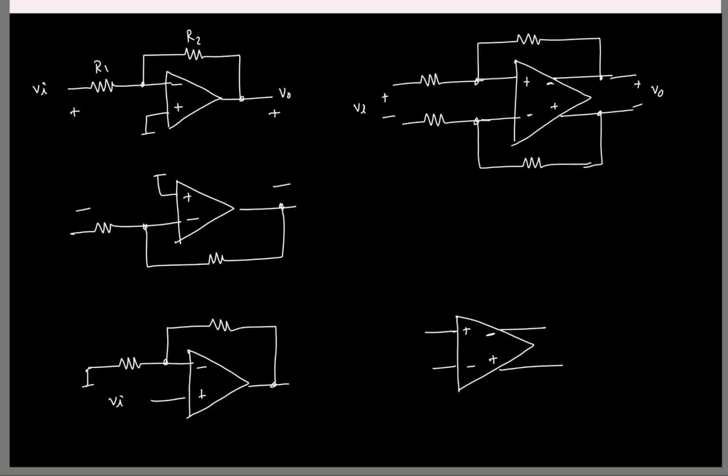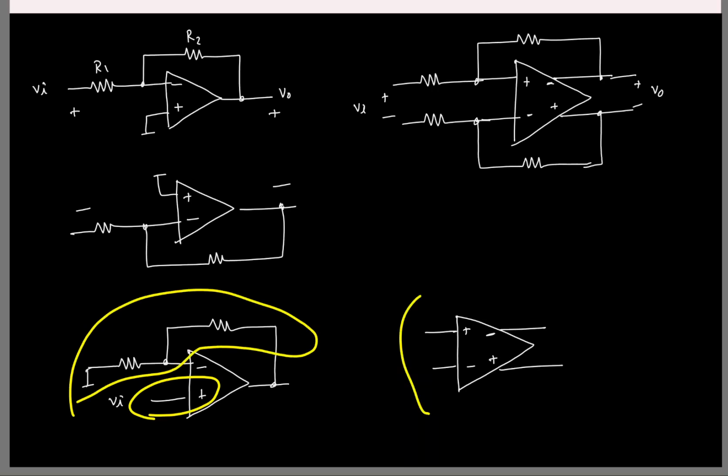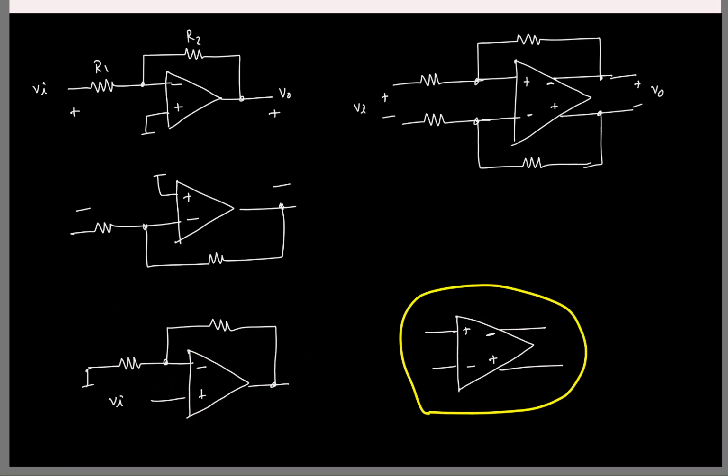So in the single-ended case, how was the non-inverting amplifier formed? We apply the input to one of the terminals and the feedback is formed around the second. So can we do something like this here? I mean, if I assume that the input is applied here, this will be used for feedback, or vice versa, right? So bottom line, we can't form a non-inverting amplifier with this. Okay. So you can't. I mean, this you can do, but this you cannot form.